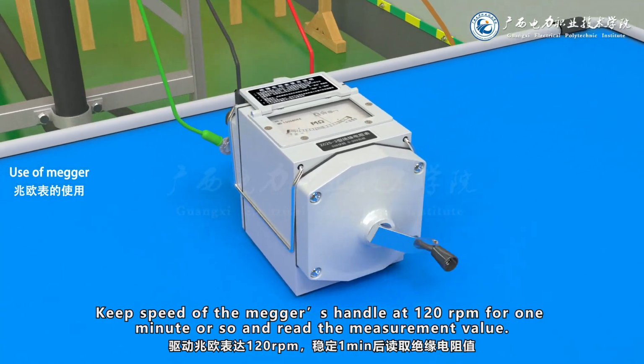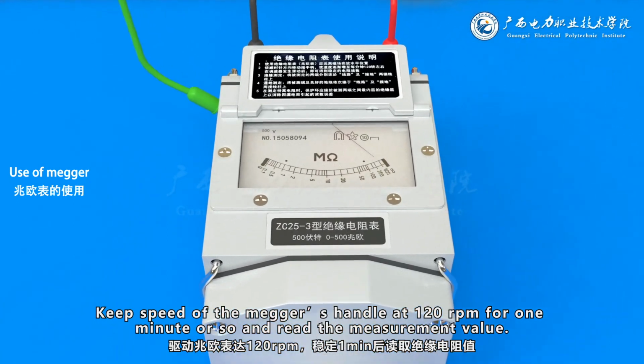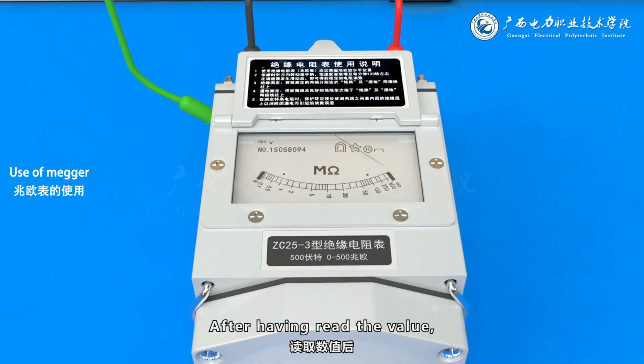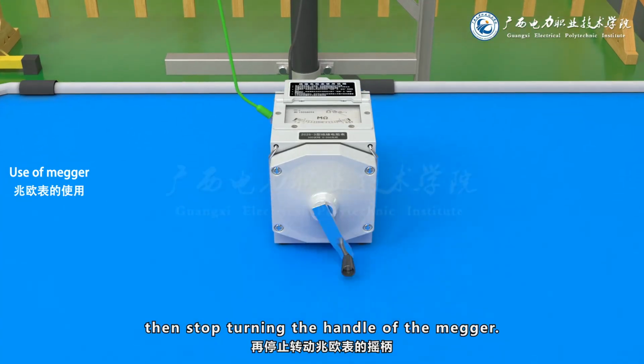Keep the speed of the Megger's handle at 120 rounds per minute for 1 minute or so and read the measurement value. After having read the value, you should disconnect the L terminal wiring first, then stop turning the handle of the Megger.